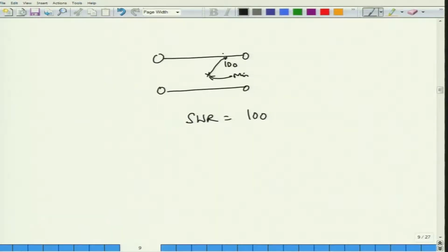If that happens, the material of which the transmission line is made and the structure in which the transmission line exists can actually suffer breakdown, or these large voltages can cause breakdown or voltage hotspots, right. So, there will be a voltage hotspot at which the voltage is maximum, then there will be a voltage minimum. Voltage minimum is reasonably okay. We are okay with the voltage minima, but this voltage maxima is pretty bad for us. These are all the hot spots that I have.